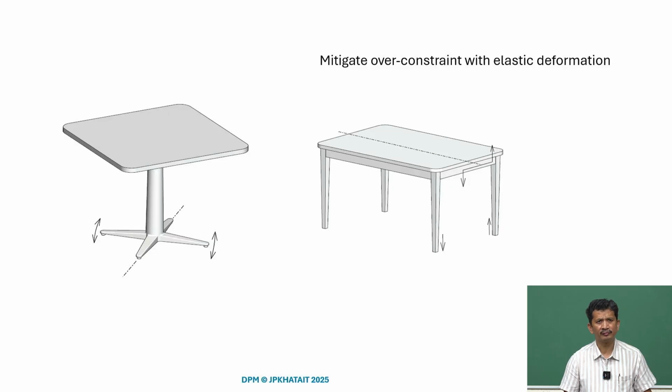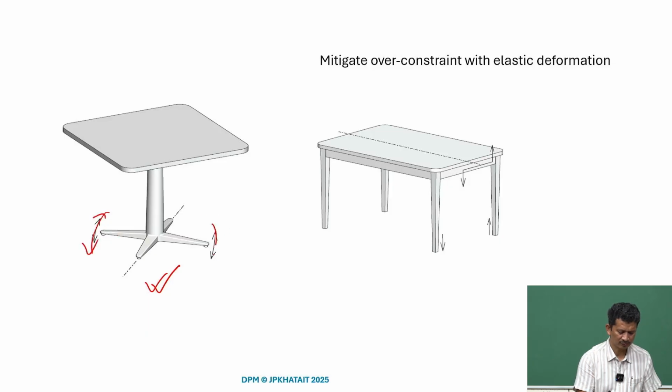What we also observe is that the four-legged table is not a stable solution. In this case, this pedestal has 4 supports, and yes, the exact constraint with the 3 points is valid if it's a rigid frame or rigid object. Here, if it's rigid and we have 4 points, we will have a problem and it will always rock, because we are talking about now 4 points.